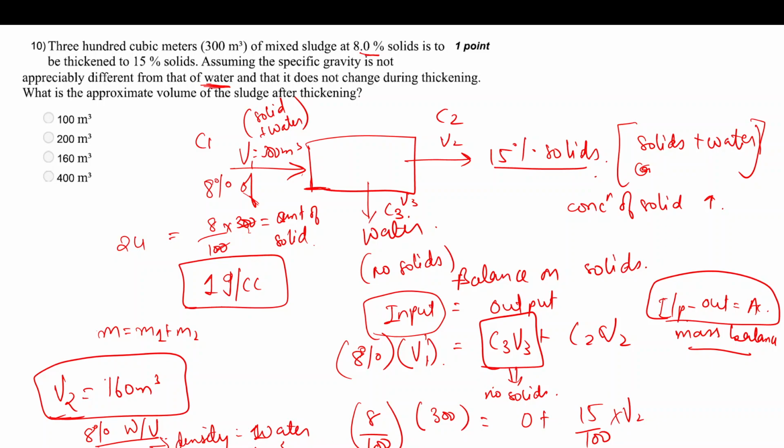you have a corresponding 1 kg of solid, or 1 kg of weight of that water. So in this case, the conversion will be the same. But if the specific gravity is not the same, then you need to convert the volume into mass using density, and convert again. That sort of conversion you need to have if the specific gravity is not the same as water.